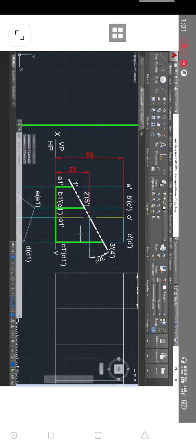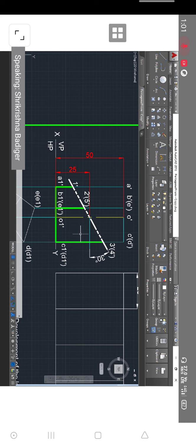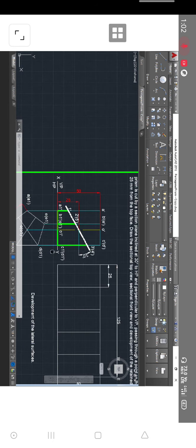Okay, do you see now what I'm doing? Now we are reaching the completion of the front view, the sectional front view. When we do this much, we can say we have done all the elements which are just construction with the 2H pencil, then the section plane, and its inclination, where it is cutting, and so forth. These are 1 dash A1 dash, 2 dash B1 dash, 5 dash E1 dash, and 3 dash C1 dash, 4 dash D1 dash. When you show that and make this a visible edge, that completes your front view.